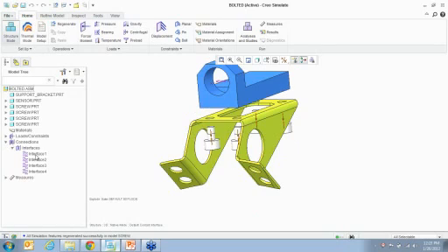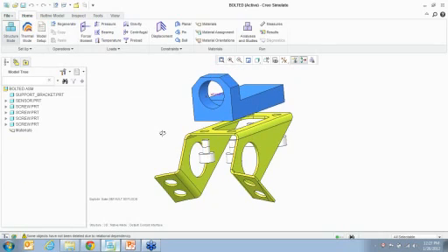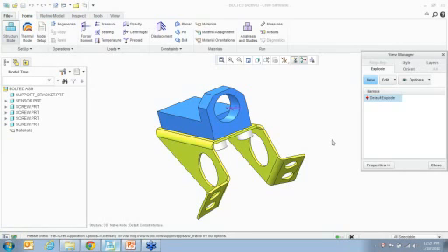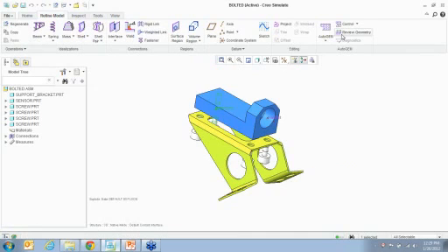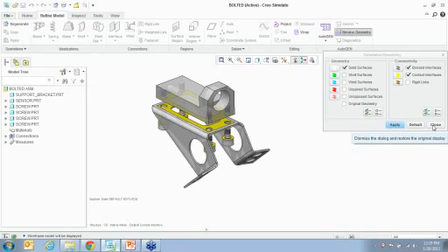All right. So notice that this assembly is in more of an exploded state. I can go back and pick the interface between the hole into which we work in the exploded state of the assembly. Also notice the Mechanica model setting says everything is under contact. Those are your interfaces, and you can see in that gray individually contact to say bonded or free or whatever you want.